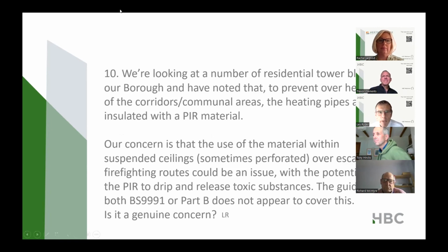Right. We're looking at a number of residential tower blocks in the borough. This has come from a London borough, and they have noted that to prevent overheating in the corridors and communal areas, heating pipes are insulated with a PIR material. Our concern is the use of the material within suspended ceilings, and the suspended ceilings are often perforated to keep the reverberation sound down. Over escape and firefighting routes this could be an issue, with the potential of PIR to drip and release toxic substances. The guidance in both 991 and Part B does not appear to cover this.